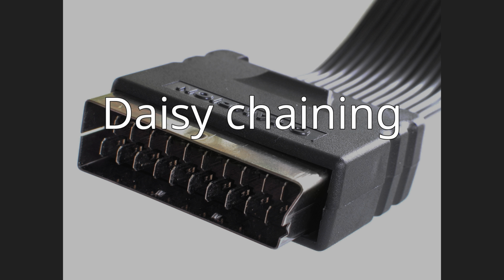Logically, the TV is on top and ends the up chain path, translating the electrical info into an image and sound. From the same logical point of view, the info stream, wherever it originates, may need processing such as decrypting, decoding, descrambling, or adding captioning/subtitles. In this case, the info stream is sent logically down to dedicated function devices. From the last processing device, the info stream is sent logically up to the TV through all the chain path. Another case is when the info stream is sent down and not expected to be sent back up, for example, when sent to a recorder. Closing a loop on either the up or down chain path may not have useful effects and may create instability.